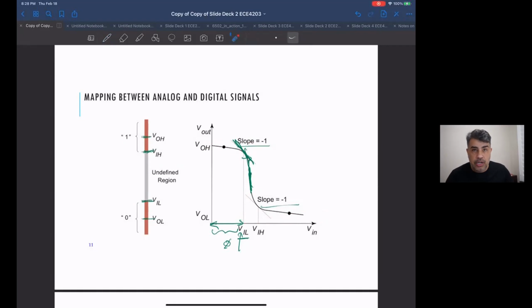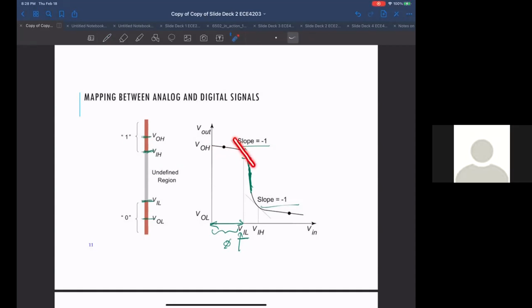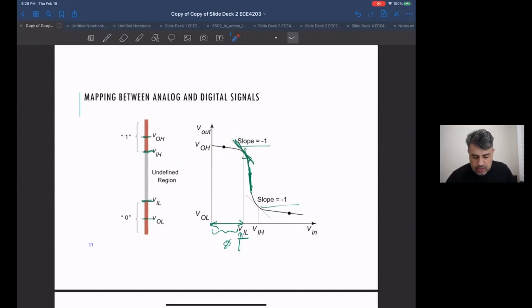That's like an amplifier. That's not what you want. So you want to stay below the slope of 1. The -1 is incidental. You want to stay below a slope of 1. If you're at a slope greater than 1, it means you're gaining up your input at your output. See what I'm saying? And the fact that it's -1 is just because it's pointed in this direction.